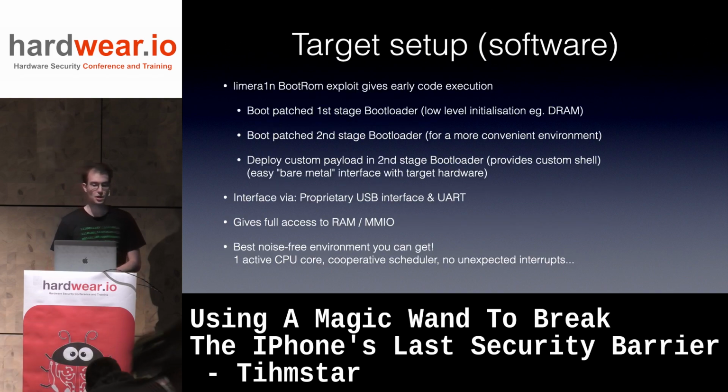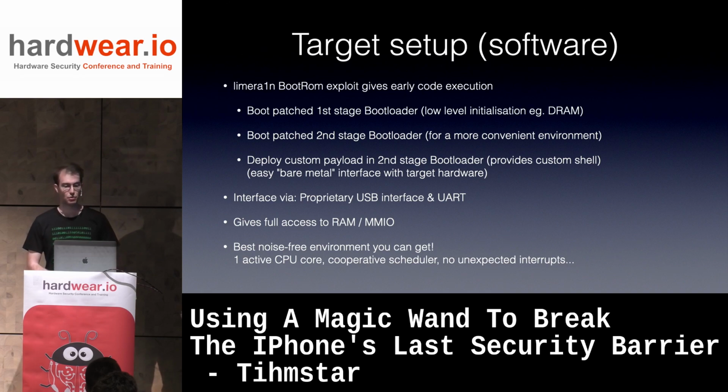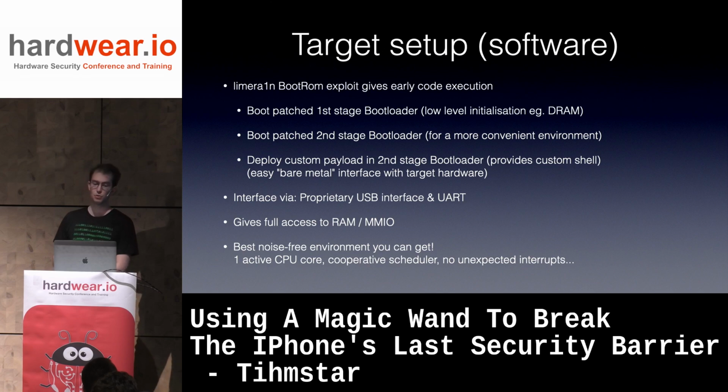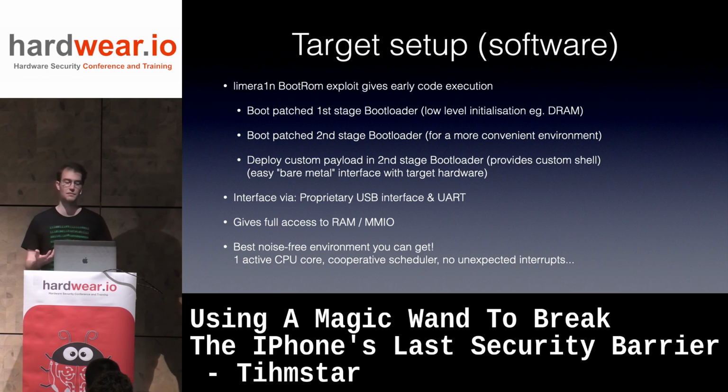So let's take a look at the target setup, software side. I use the limera1n bootrom exploit to gain early code execution. I boot a patched stage 1 bootloader, which does low-level initialization like DRAM, for example. I boot a patched second stage bootloader for just a more convenient environment to work with, because iBoot actually has a custom shell, so if you do a little patching, you can run your own payload there, bare metal, but still with some functionality already available like printf, UART, and stuff like that.